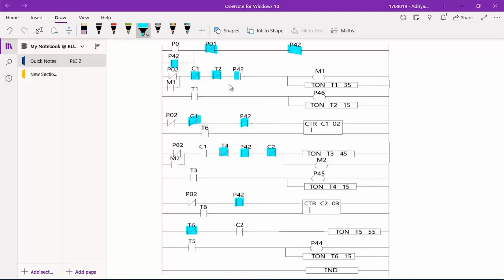Now if we put another object, the second object, onto the conveyor belt, after a certain period it will get sensed by the sensor P2, and like before, all the P2 across this ladder logic diagram will receive signal. Whenever P2 receives signal here, this counter will count to 2. This counter will also count to 2. Now if we look at here, in this counter, the initial count we set was 2. So the C1 will be activated and hence it will receive signal.